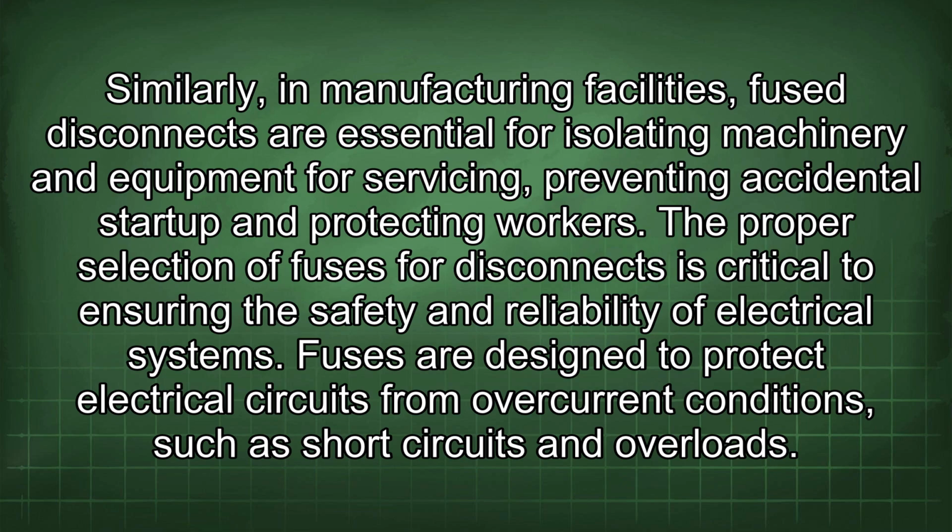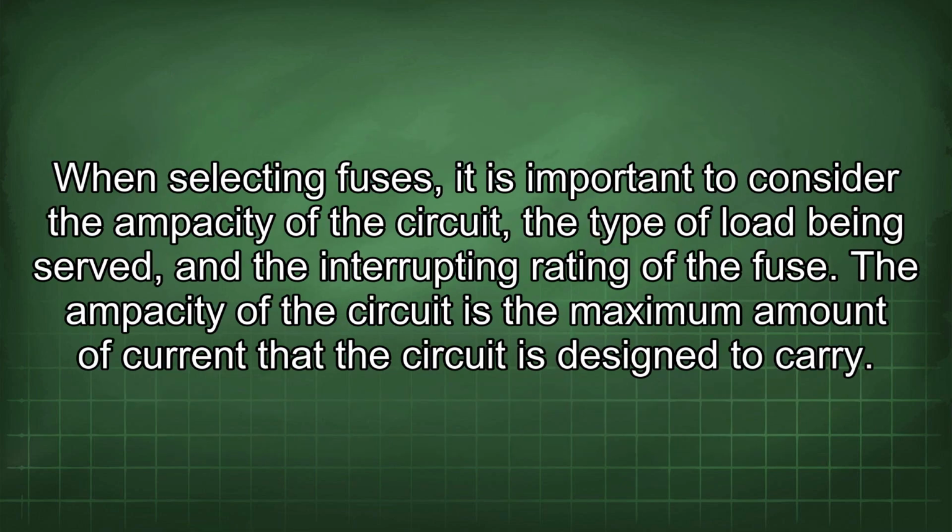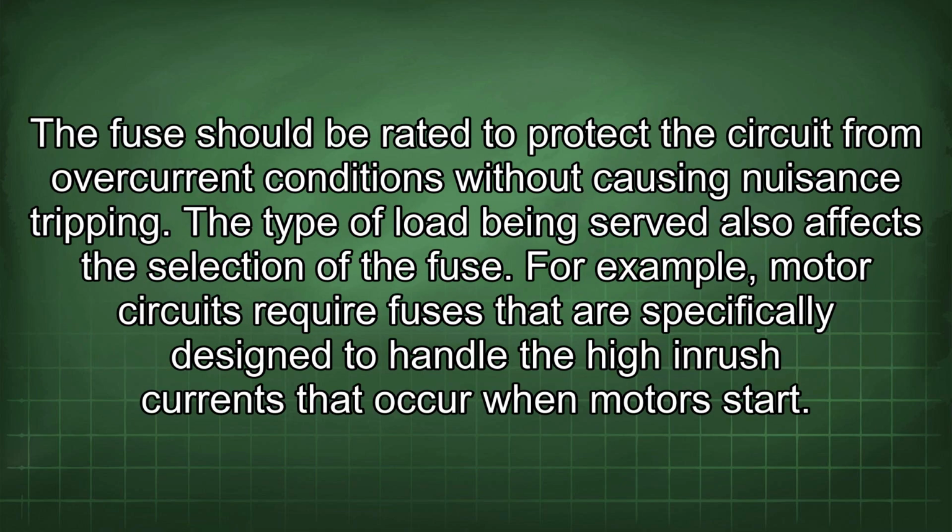Fuses are designed to protect electrical circuits from overcurrent conditions such as short circuits and overloads. When selecting fuses, it is important to consider the ampacity of the circuit, the type of load being served, and the interrupting rating of the fuse. The ampacity of the circuit is the maximum amount of current that the circuit is designed to carry. The fuse should be rated to protect the circuit from overcurrent conditions without causing nuisance tripping.